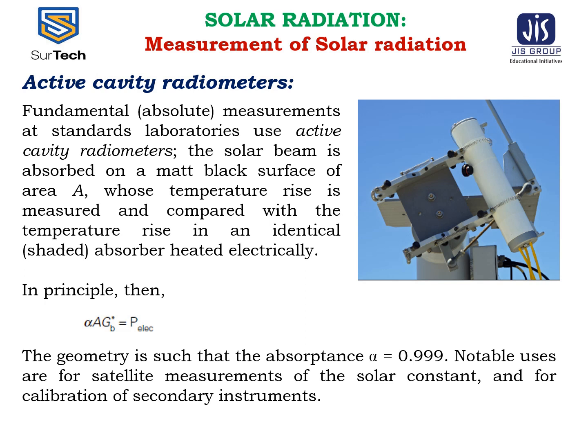The methods of measuring heat include taking out the heat flux as a temperature change, using a water pyrheliometer, a silver disc pyrheliometer, or a bimetallic pyrheliograph, or as a thermoelectromotive force using a thermoelectric pyrheliometer or a thermoelectric pyranometer. In current operation, types using a thermopile are generally used.